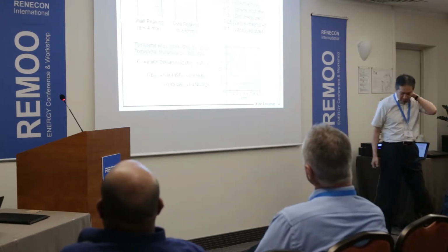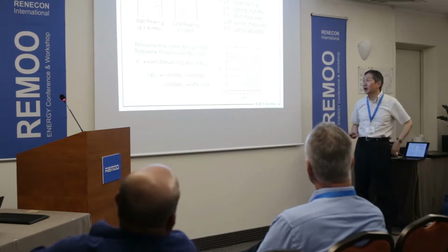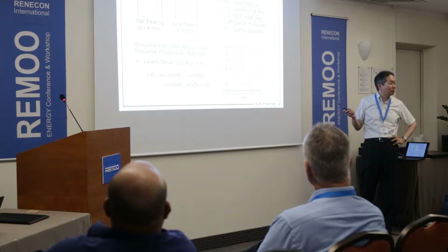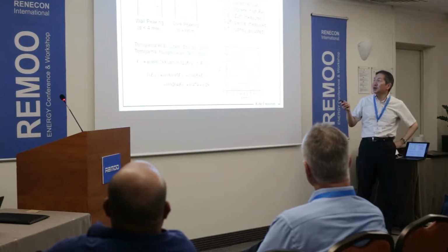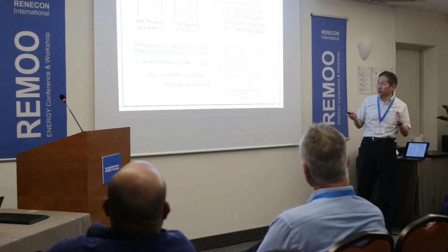We've also done lots of experiments because, as Mike already mentioned, in the past we relied on a lift coefficient value of 0.5, but many people claim that there is some difference in the value. If we look at the void distribution in a pipe flow, we have wall peak in the case of an air-water system.